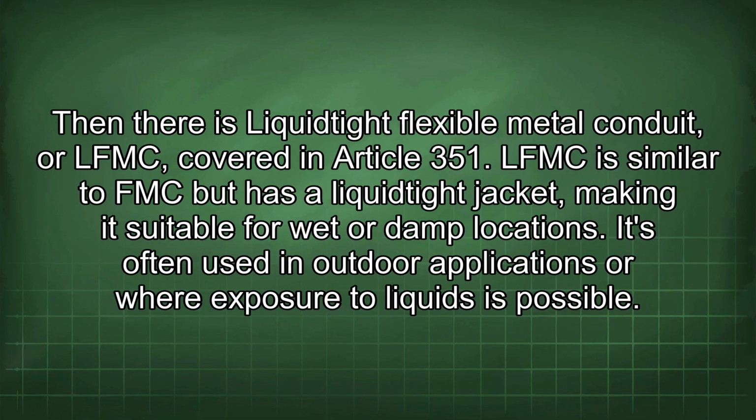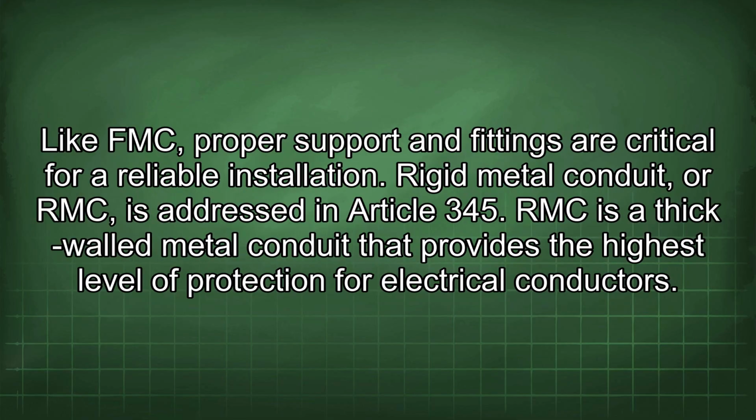Then there is liquid-tight flexible metal conduit, or LFMC, covered in Article 351. LFMC is similar to FMC but has a liquid-tight jacket, making it suitable for wet or damp locations. It's often used in outdoor applications or where exposure to liquids is possible. Like FMC, proper support and fittings are critical for a reliable installation.